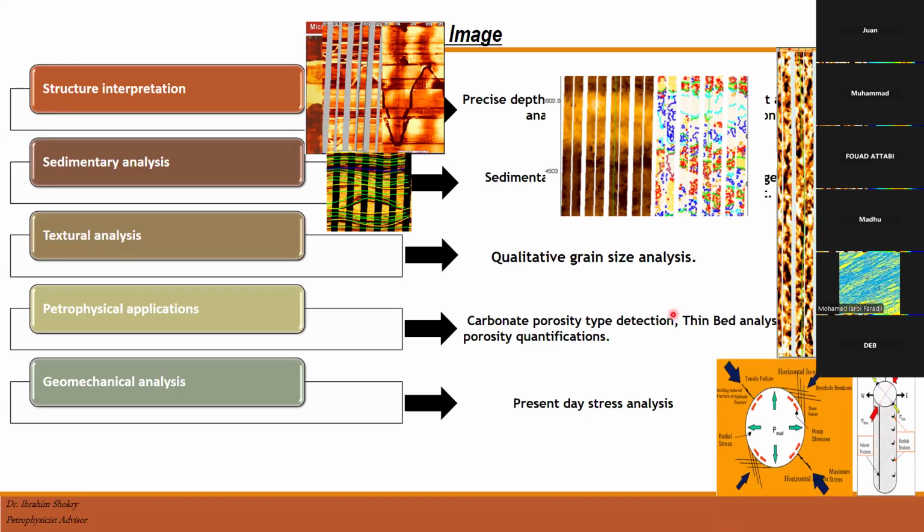The fifth application of our borehole imaging is regarding mechanical studies. By using the images we can determine the maximum horizontal stress and the minimum horizontal stress, using the induced fractures and breakouts. These values will be very useful for the engineering team in order to plan a frac job or something like that.